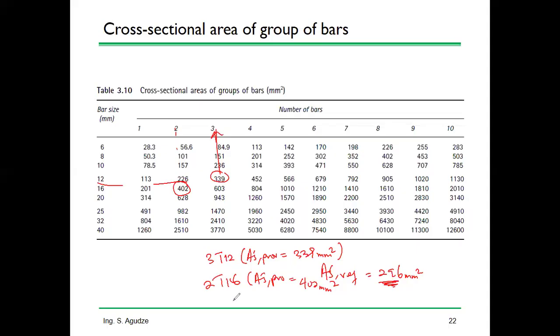You should understand that design is both an art and a science. So you have to be creative, you have to be artistic. Whatever you are selecting, you should include engineering judgment: whether the thing can be fixed on the site, whether when we cast the concrete it will be good enough, whether the spacing is fine. You have to look at all these things and decide on a number of bars. If the number of bars is too many and is not giving you the chance, you have to change the bar size or adopt paired or bundle bars.